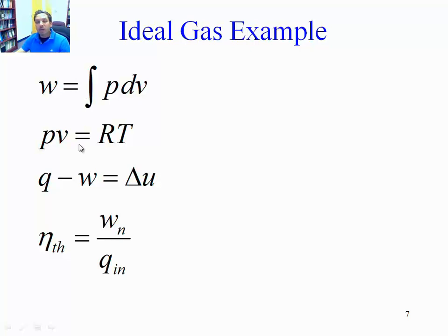We know that the state equation, because CO2 is an ideal gas, this always applies. PV is equal to RT. Or we can just say that the ratio PV divided by T always remains constant on any process. PV divided by T is always a constant on any process, regardless of whether the process is isometric, polytropic, isentropic, isobaric, isothermal. PV divided by T is always a constant.